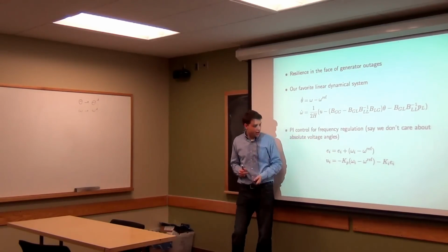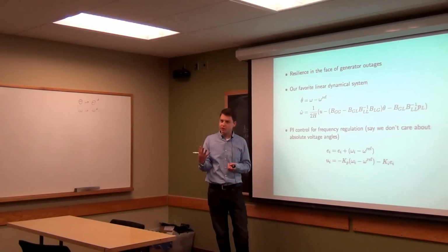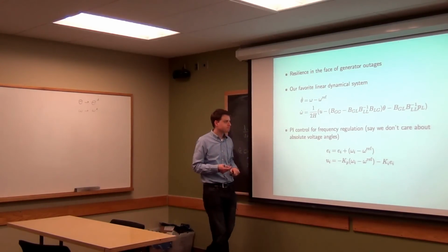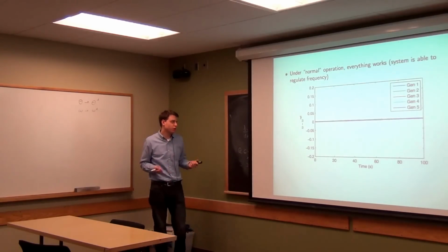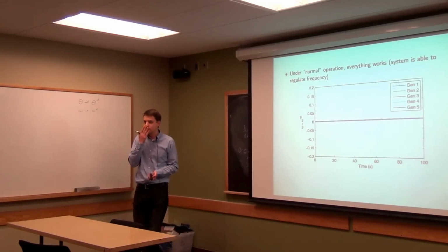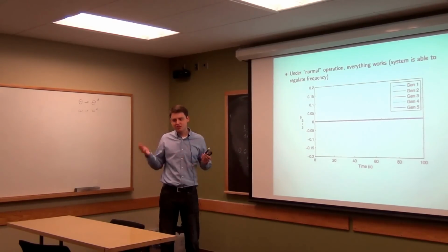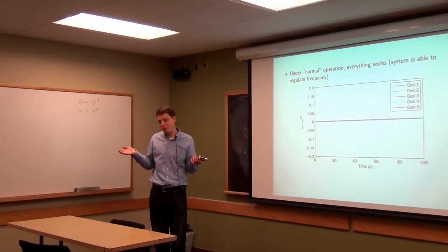And if we take our scenario, the 14-bus system with 5 generators that I was using before, we're going to use that same one again and see what happens. This works. I picked some gains. They didn't take too long to find gains that worked here. Each generator just says, okay, I'm going to look at my frequency, I'm going to act based on that, and then see what happens.